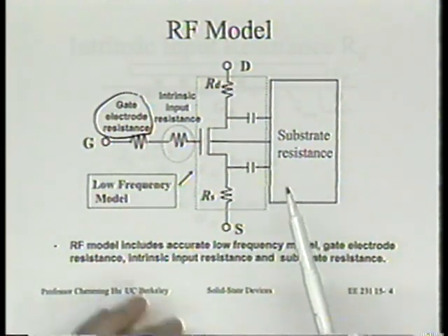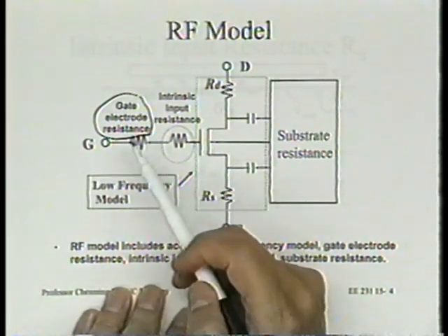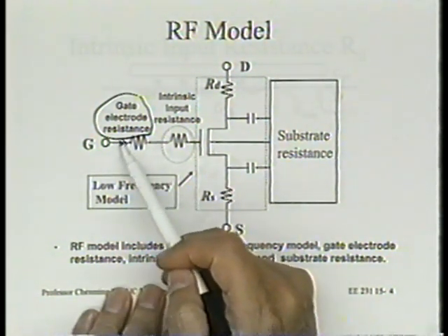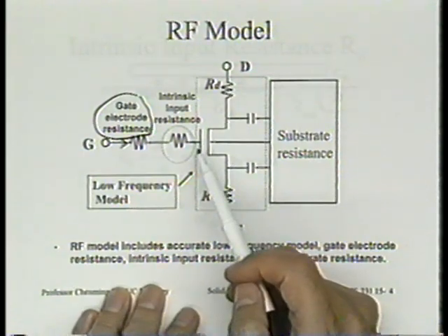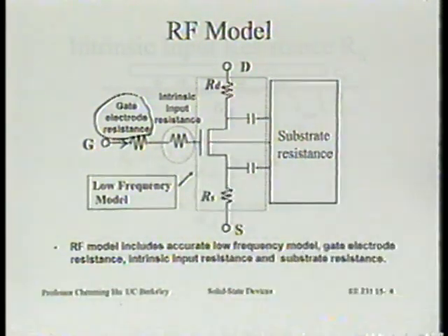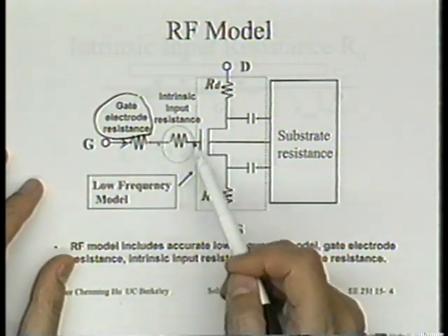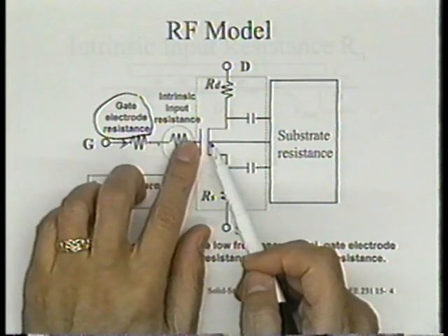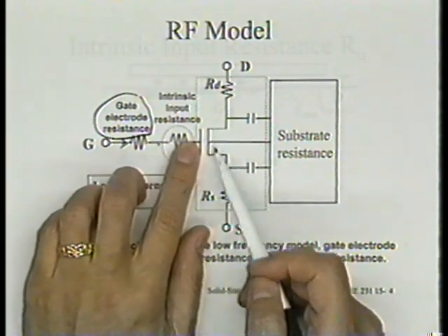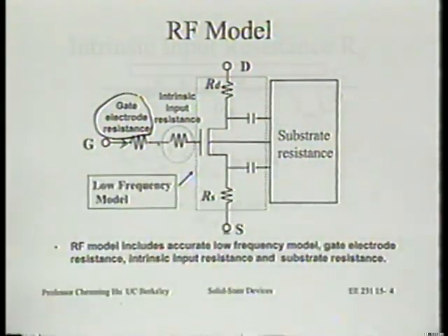Well, it turns out it's very simple. The reason is at RF frequency, there's a significant amount of current flowing through the gate, right? Just because of gate capacitance, there's current. Because of this gate current, there's going to be a voltage drop across the resistance in the gate. As a result, you don't see the full voltage across the dielectric, so you don't get as large a GM, and your performance is degraded. Simple as that.